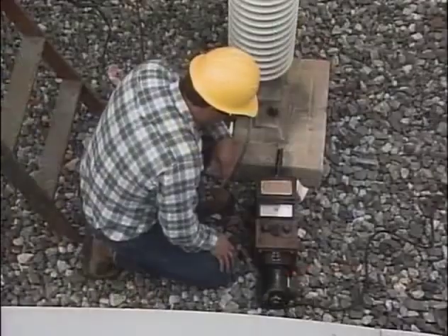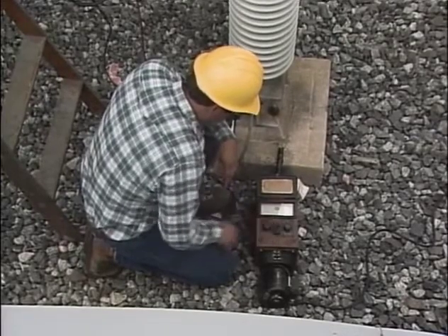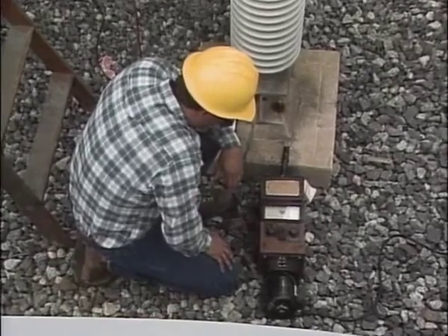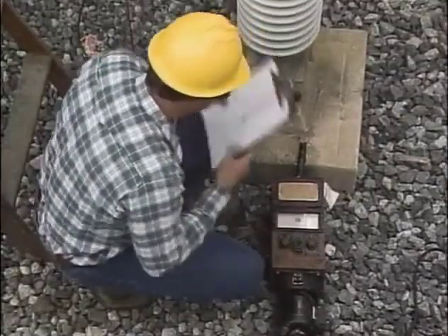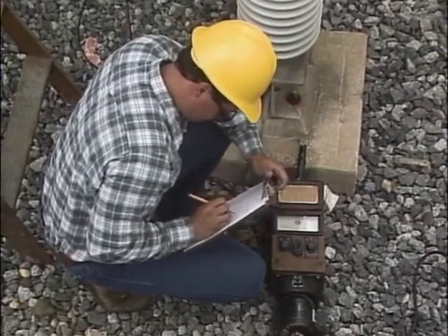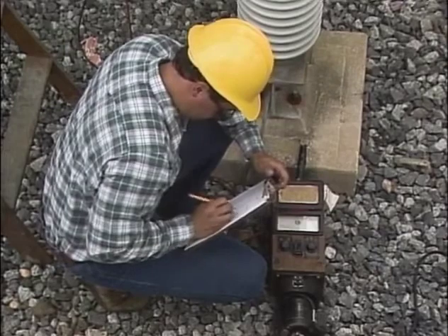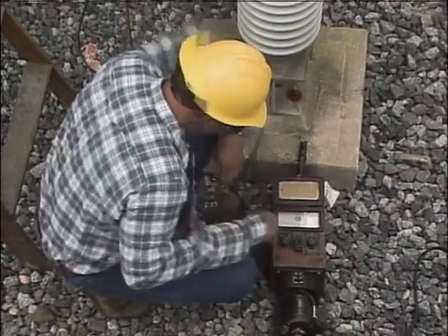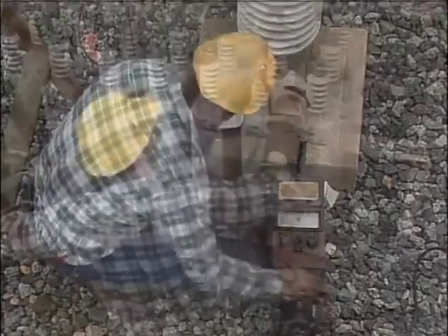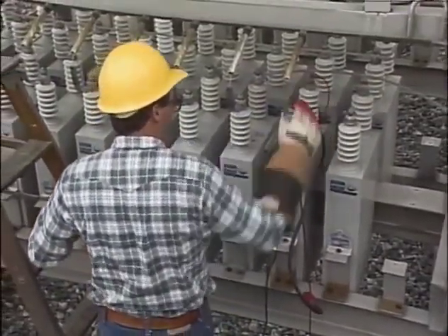With the voltage range of the megohmmeter set below the rated voltage of the capacitor, the megohmmeter is turned on to apply voltage to the capacitor. The resistance indication is allowed to stabilize. Then it is documented. If the resistance is not within an allowable range, the capacitor is replaced. When the test is done, the megohmmeter is turned off. The temporary ground is reconnected, and the leads of the megohmmeter are removed from the capacitor.